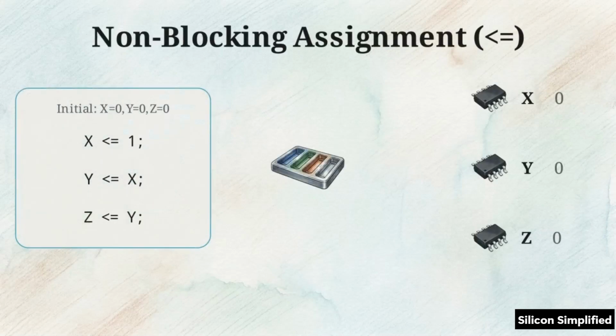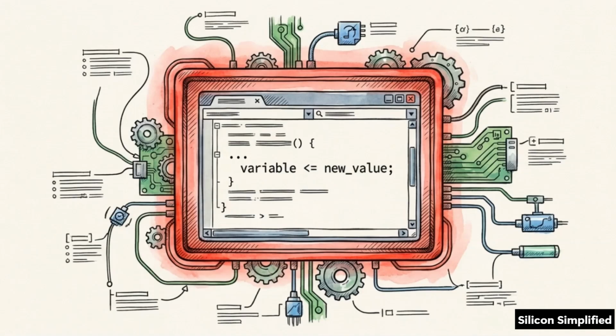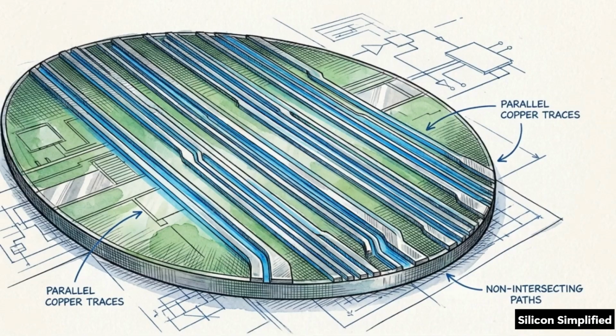Conversely, non-blocking assignments use a two-step model. In the evaluation phase, all right-hand values are captured simultaneously. In the update phase, they deploy to left-hand targets, forming distinct, parallel physical flip-flops. Because of this mechanic, RTL design relies on a strict rule: always use non-blocking assignments for clocked sequential logic. Respecting this two-step simulator mechanic prevents data collisions in the physical hardware.